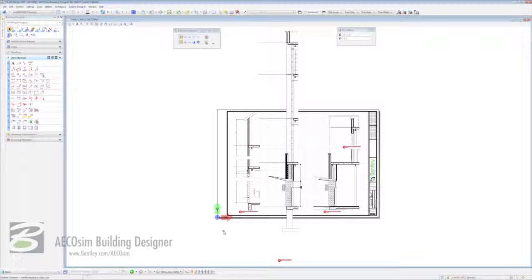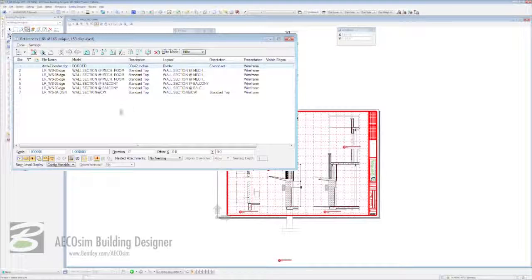Now I'm going to start bringing in the power of Building Designer and the utility of references, because we're going to come to our primary taskbar and open up our references, and our reference dialog box opens, and you can see here that we have, if I click on it, it highlights for us, this is our section file, but I need to copy it because we need to put a break line in here and have a new detail of the plinth in the top and the parapet.